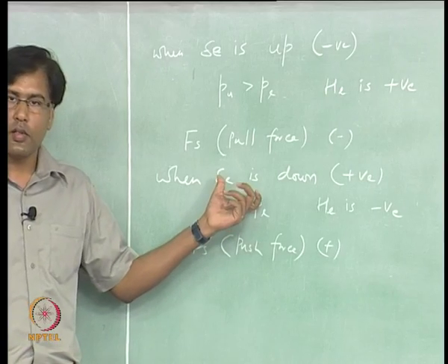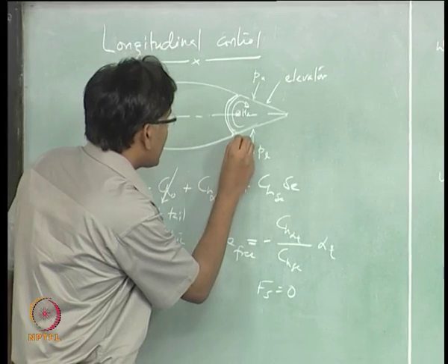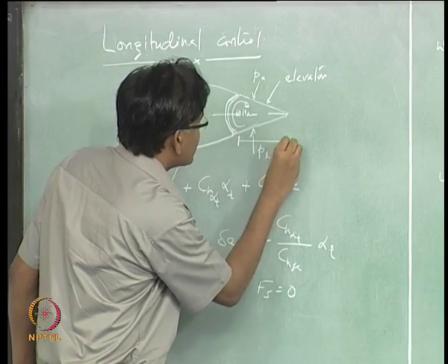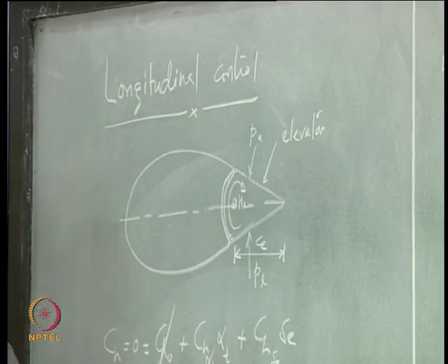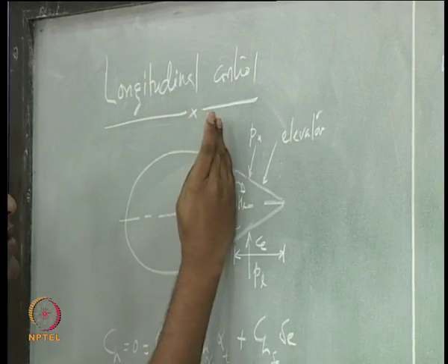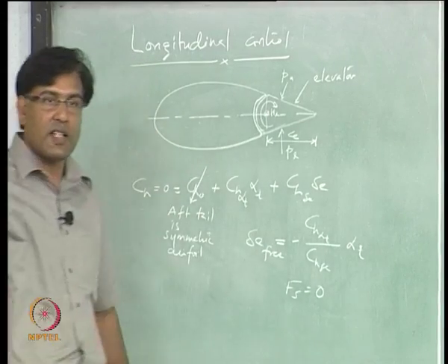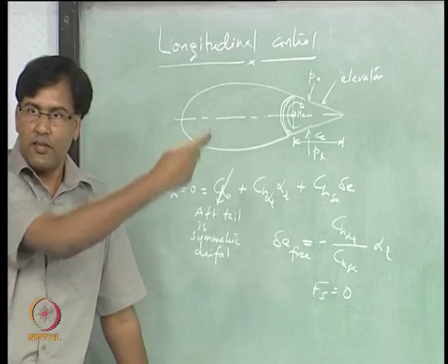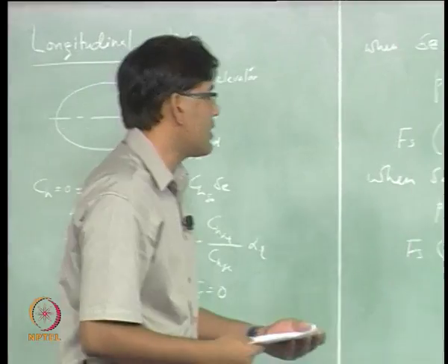Required to deflect the elevator down, right. All right. Okay, but if you remember, we have been talking about the hinge moment considering this as the reference chord, right. This is where this whole action is taking place, right, pressure. Now I can only talk about the force distribution behind this hinge line, isn't it, and that moment only I am using to define the hinge moment.